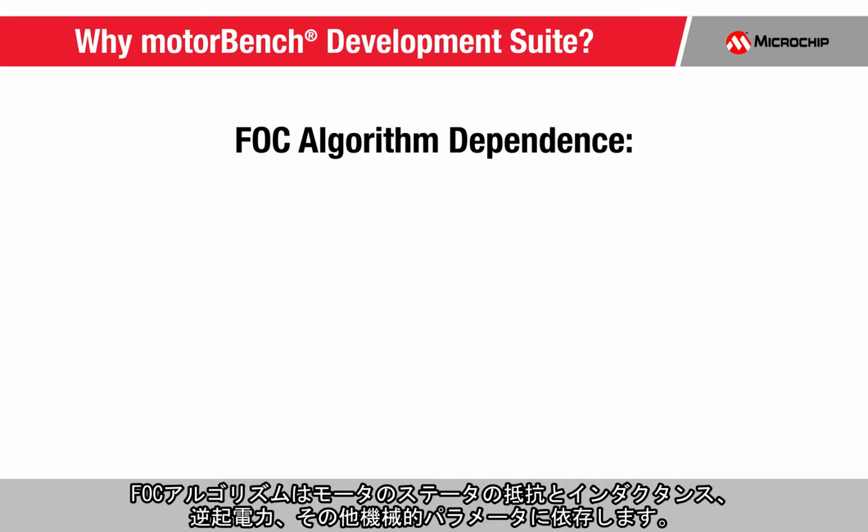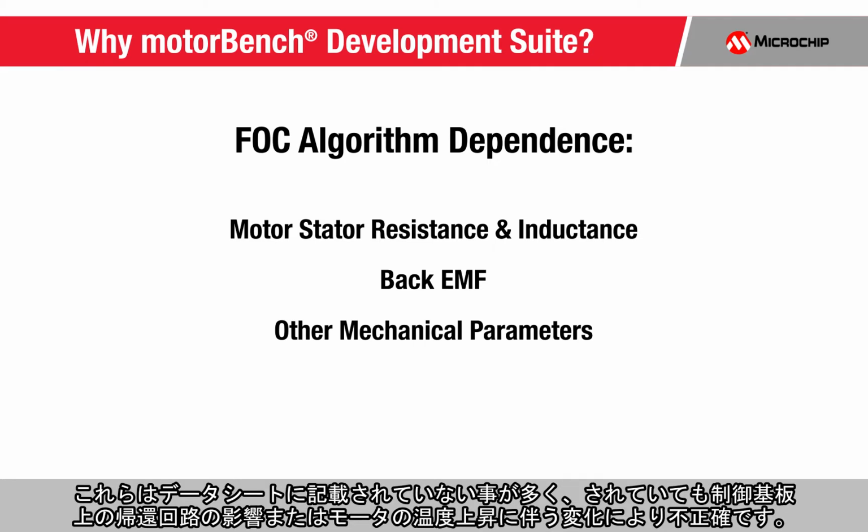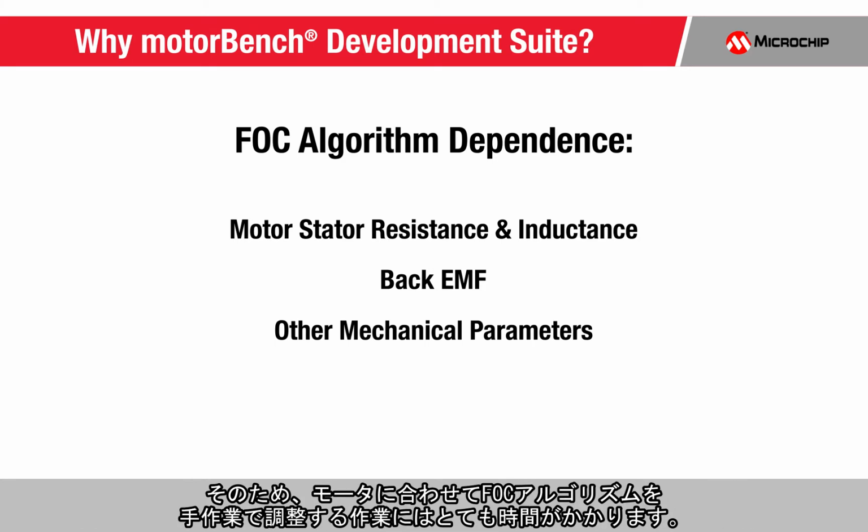The FOC algorithm is dependent on motor parameters like the motor stator resistance and inductance, the back EMF, and other mechanical parameters. Many times these parameters may not be available in the motor's datasheet or are inaccurate due to the effects of the feedback circuits on the control board or changes as the motor heats up. Because of this, it can be very time-consuming to hand-tune the FOC algorithm for your specific motor.